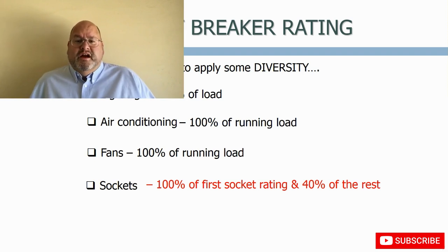There is no standard on what diversity factor you need to apply. It really comes down to your knowledge of your own system. When designing a system, write down what diversity factor you've assumed and why. When the system is energized, monitor the current levels at various points to make sure that your diversity assumptions were correct. If the current is widely different to what you assumed, then change your diversity factor on the next design.